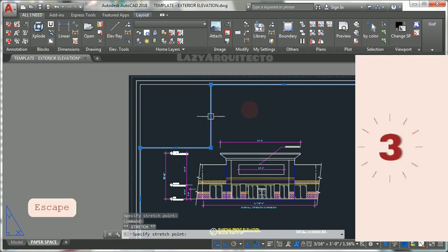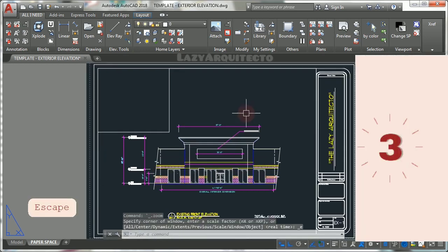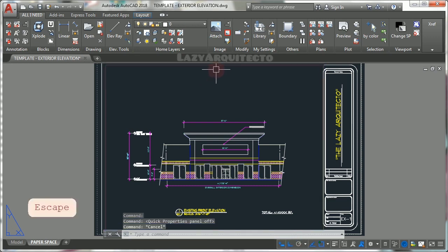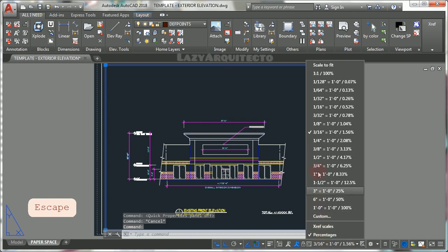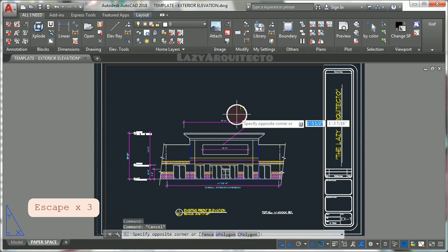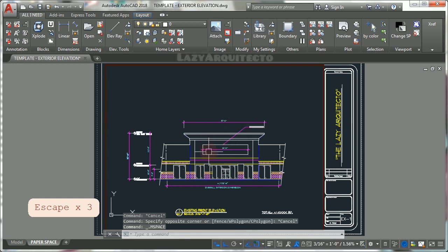Number 3. Make sure you know how to quickly create viewport custom scales. This is key because there will be moments where you don't have the correct viewport scale available in your specific drawing. For example, let's say you don't have 1/8 of an inch scale in your drawing.